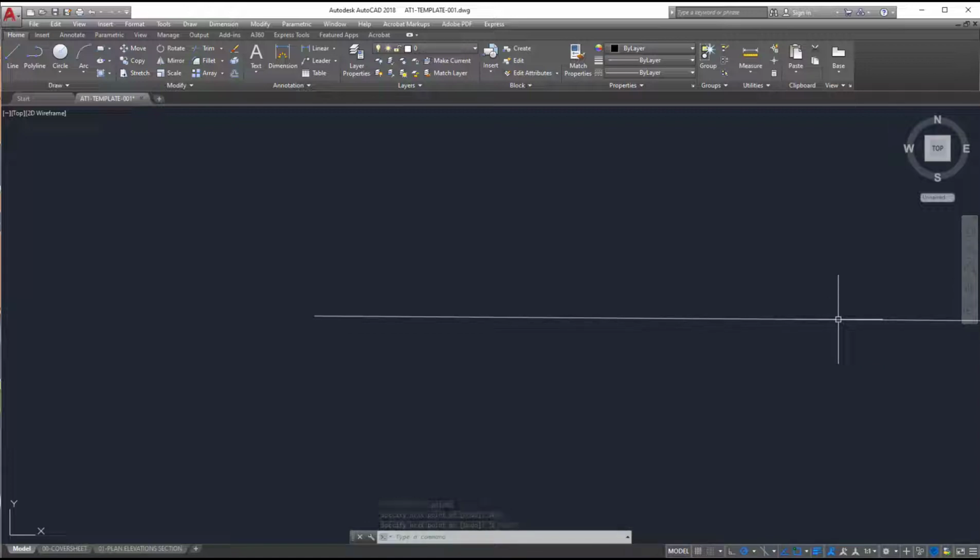Remember that in AutoCAD, and in basically all Australian drafting convention, bar say rail or perhaps surveying or civil, which denote measurements in meters, architecture, engineering, and most building construction is definitely all in millimeters. So we've just drawn a line that's 3 meters long, and then hit escape to complete the command after hitting enter.